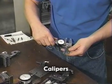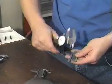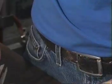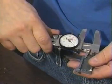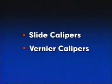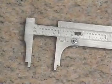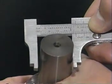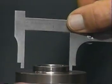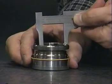Graduated calipers are a refinement of the steel rule and make it possible to ensure greater accuracy by contacting edges or points to be measured. The primary types of precision graduated calipers used for measuring and gauging include slide calipers and vernier calipers. Slide calipers have a bar which is usually graduated and a pair of jaws that contact the part. One jaw is fixed and the other moves along the scale. Slide calipers are graduated to read outside surfaces and inside surfaces.